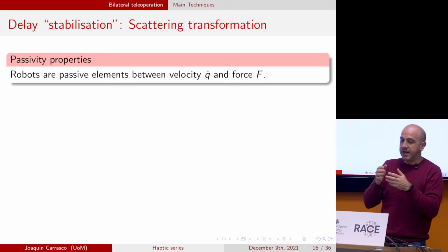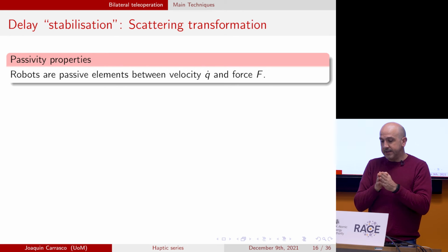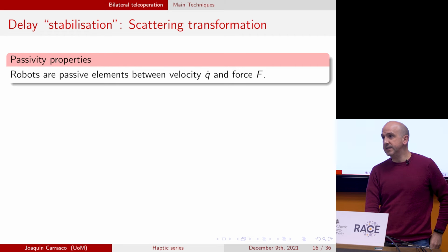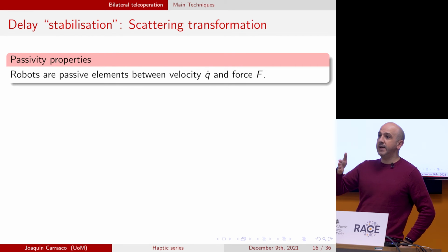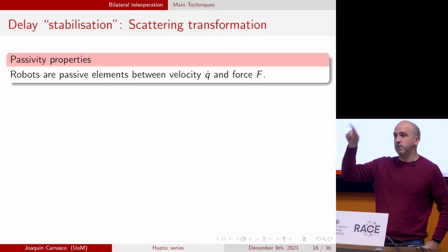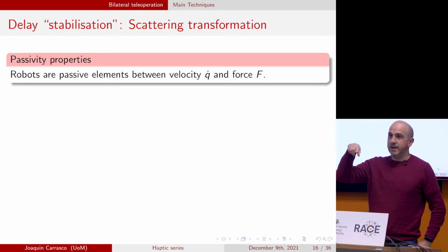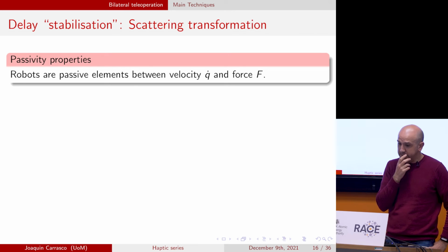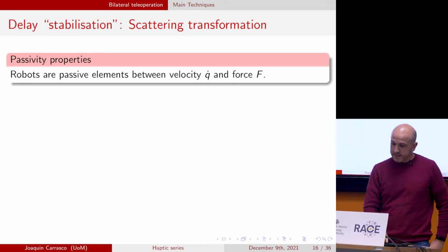In the center, I have this delay that for sure is not going to be passive, because the phase of a delay is just the product of the time delay multiplied with the frequency. So for sure, this will look like a circle of radius 1 in the Nyquist plot. Therefore, this is not passive. But what we can use is that the gain of the system is 1.